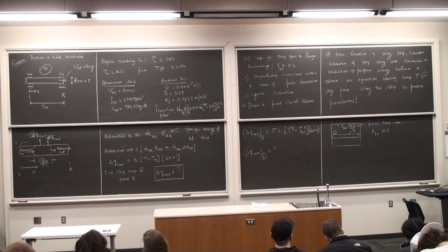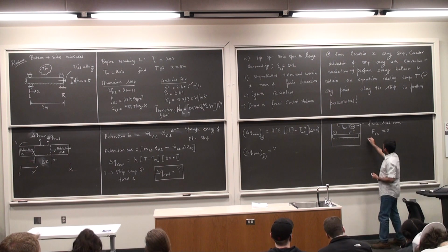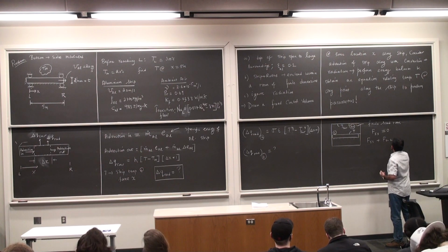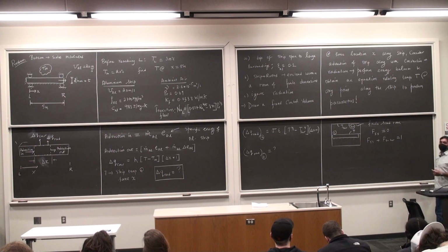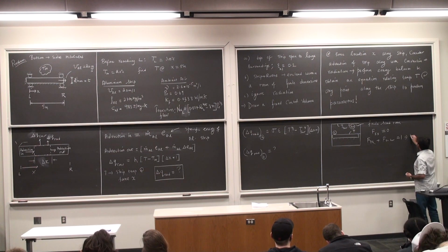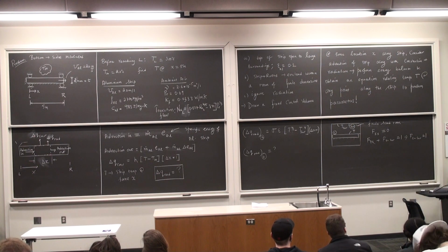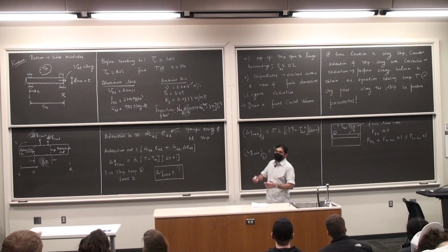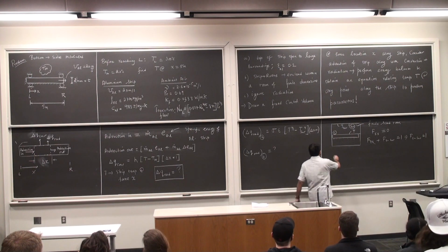There are only two things communicating here. So F S S, F S surrounding put together is equal to 1. This is the summation rule. F S S is 0, so I have F S surrounding is equal to 1. So this is the view factor. Obviously, I know the area of the strip delta x times 1, so this is delta x.